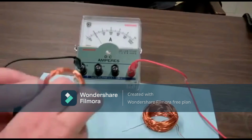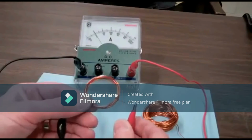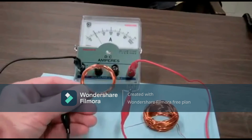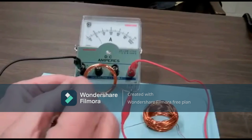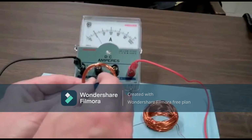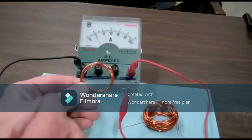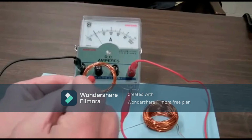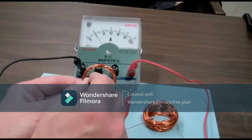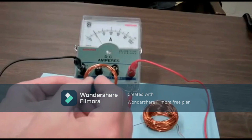So now we'll connect the 10 loop coil and we are going to do the same thing. We are going to move the bar magnet in and out of the coil. Now you can see more movement of the needle. If we go very slowly, you can just see a little bit of deflection, and if we go quickly, a greater amount of deflection. Also, as the bar magnet is going in, the needle deflects to the right, and once the bar magnet is pulled out, it deflects to the left.